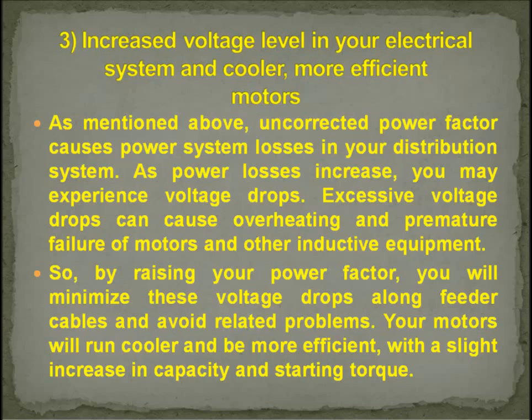As mentioned above, uncorrected power factor causes power system losses in your distribution system. As power losses increase, you may experience voltage drops. Excessive voltage drops can cause overheating and premature failure of motors and other inductive equipment. So, by raising your power factor, you will minimize these voltage drops along feeder cables and avoid related problems. Your motors will run cooler and be more efficient, with a slight increase in capacity and starting torque.